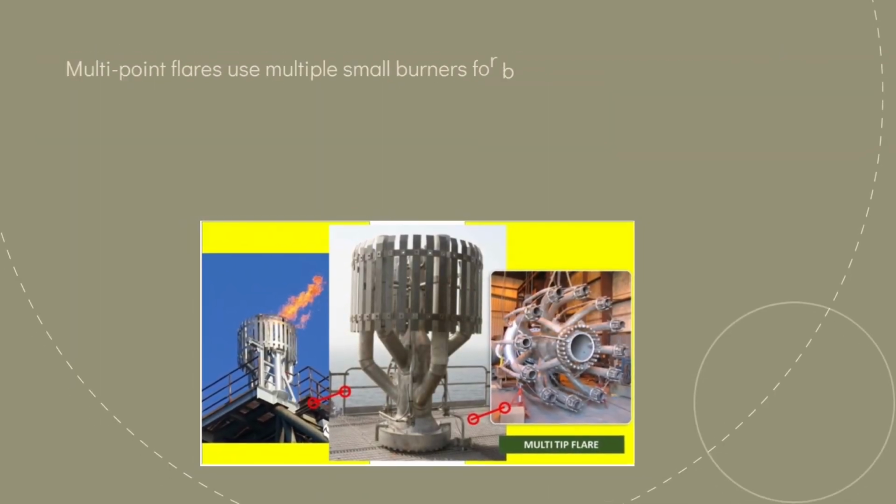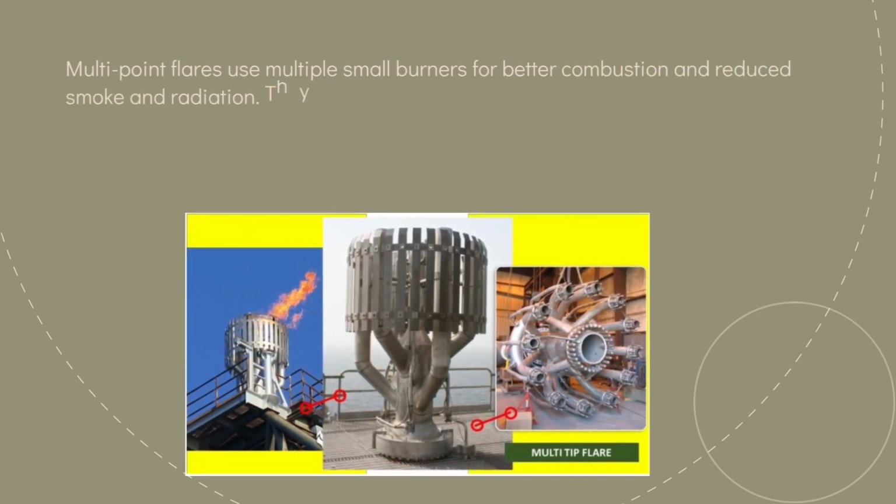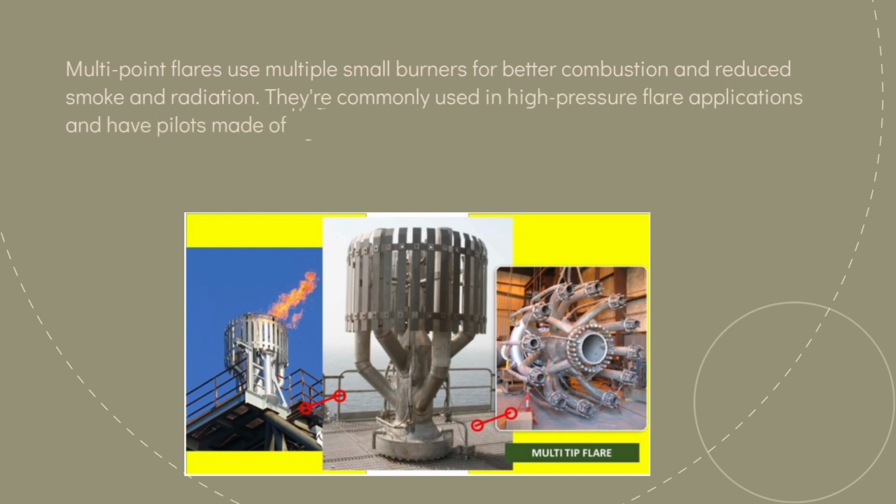Multi-point flare uses multiple small burners for better combustion and reduced smoke and radiation. They are commonly used in high-pressure flare applications and have a pilot made of heat-resistant steel and also an igniter.